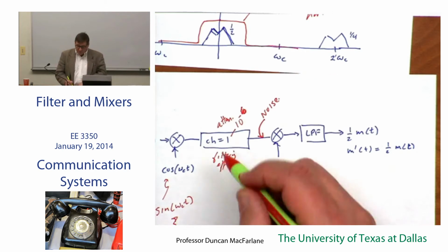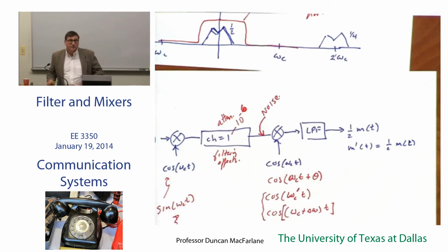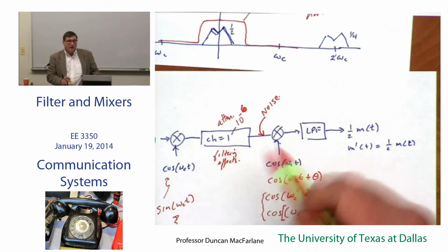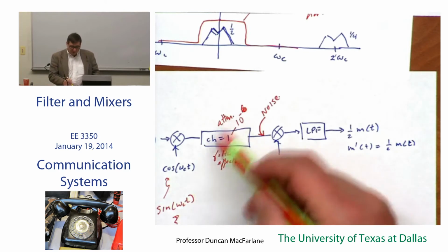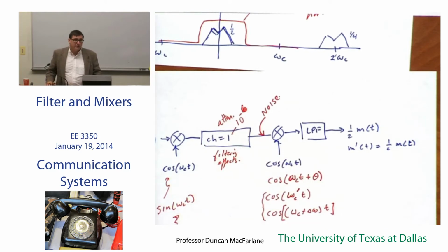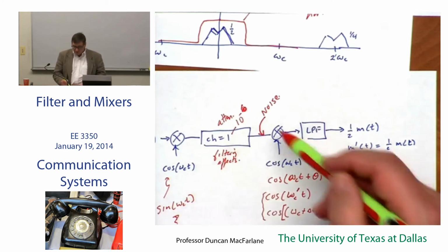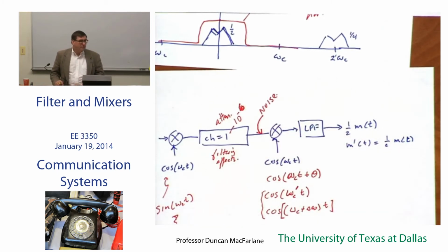Okay. So I could model that filter as some horrible filtering function. Right? This is a signal that goes through this box. The box can attenuate some amplitudes, some frequency components more than others. It can wiggle the phases around some frequencies more than others. So we can model that whole thing, that whole channel as a filter. If we know that transfer function of the filter, maybe we can do something on the back end to fix it.